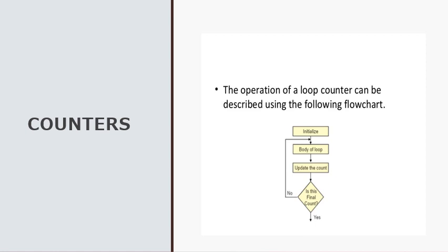First we will discuss what a counter is. Using counters, programs can specify how many times an instruction or set of instructions is to be executed. A loop counter is set up by loading a register with a certain value. Then, using the decrement and increment instructions, the content of the registers is updated. A loop is set up with a conditional jump instruction that loops back or not depending on whether the count has reached the termination count.